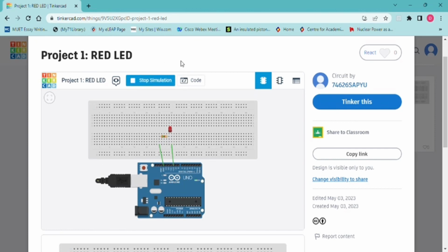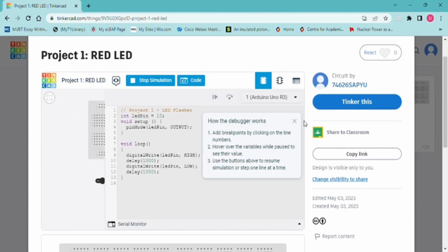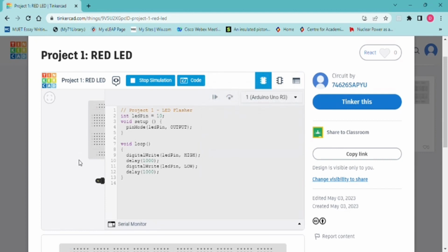Initializing, and it will light up just like that, like an ordinary flasher. The long LED is the anode of the LED, always must go to the positive 5 volt supply, and the short is the cathode, must go to the ground. Now this is our coding. You can pause the video and look further into it.